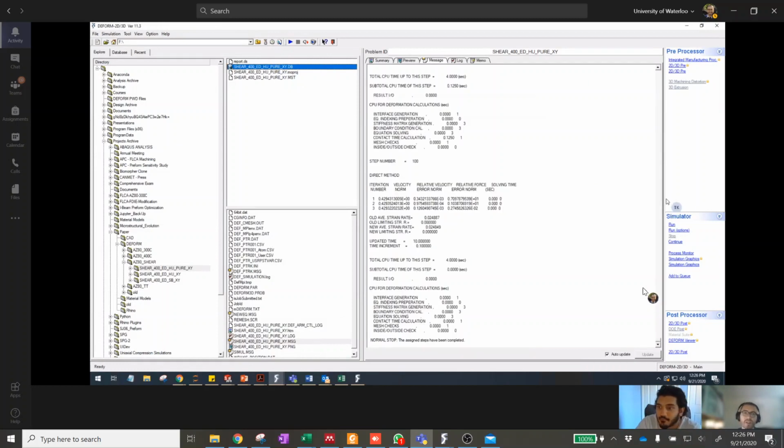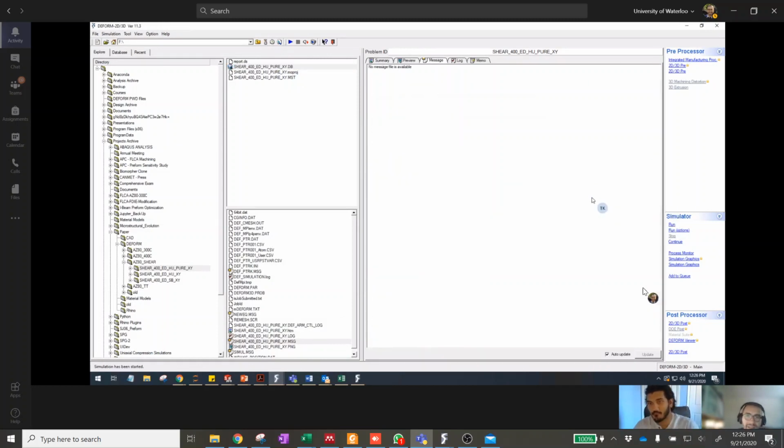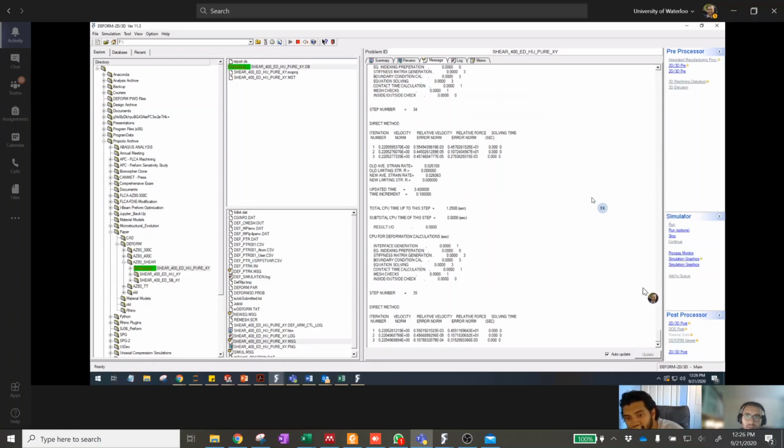So this is really a 2D problem that you're making into a 3D problem, and the way to get rid of the through thickness constraining effect is by making a symmetry plane. Hopefully, yeah, that'll be the case, because that'll make it impossible to have stresses in that direction.